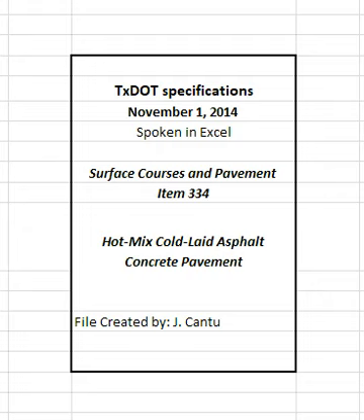4.4 Placement operations. Prepare the surface by removing raised pavement markers and objectionable materials such as moisture, dirt, sand, leaves, and other loose impediments from the surface before placing mixture. Remove vegetation from pavement edges. Place mixture on the road below 175 degrees Fahrenheit. Place the mixture to produce a smooth, finished surface with a uniform appearance and texture that meet typical section requirements.